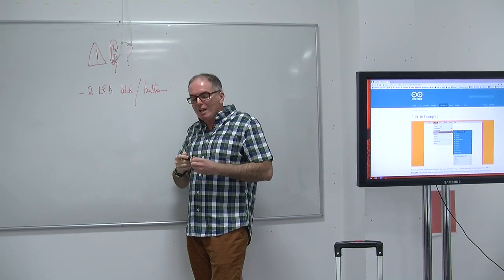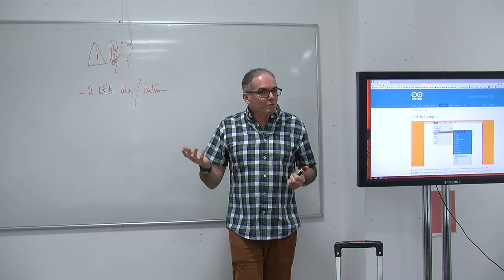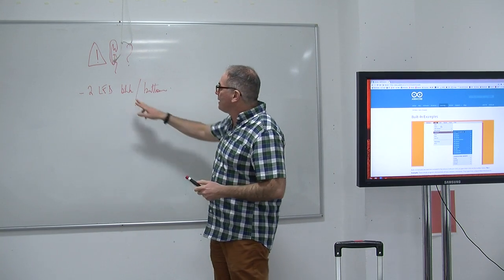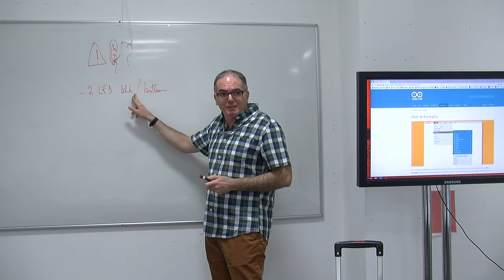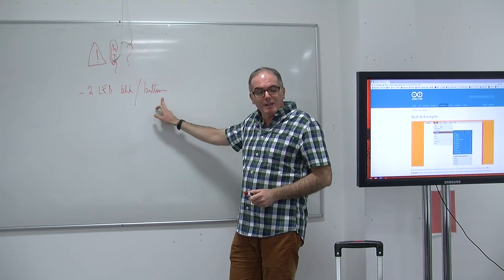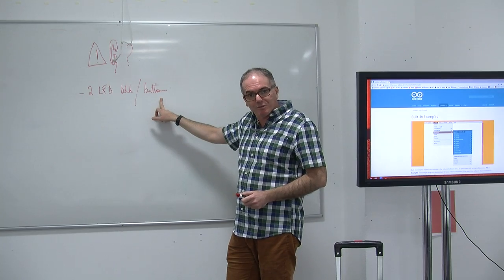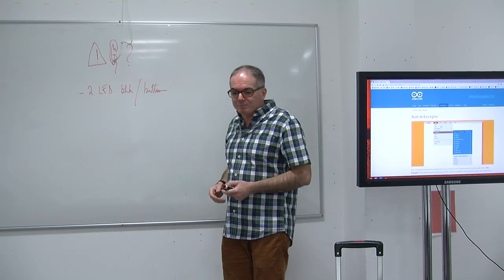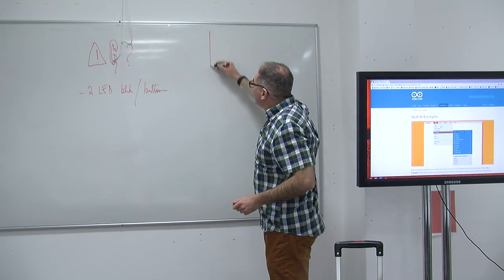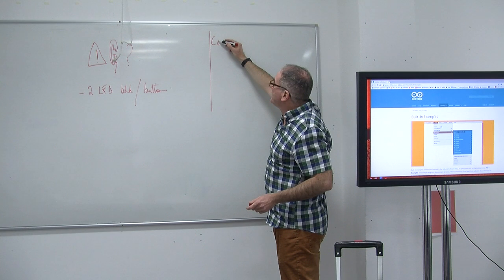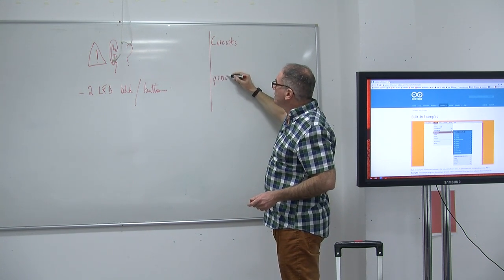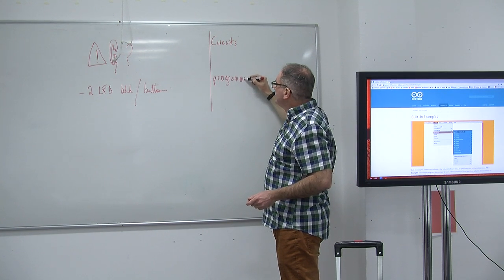it's another LED. One of the golden rules that we have is that we have to be lazy and reuse what's there. We know that the blink exercise is one of the examples in the library, and we know that the button exercise is also in the library. So we're going to combine these two. First, we have to combine two things. We have to combine the circuit, and then we have to combine the programs. Okay?